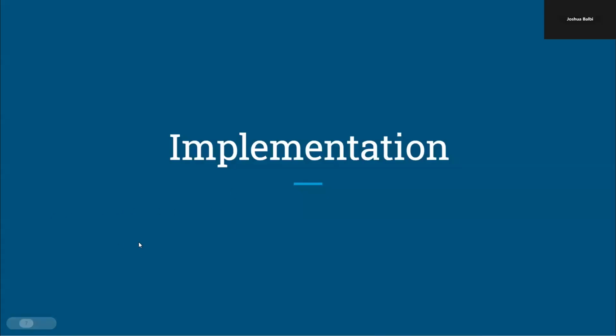So now we move on to the implementation of our project. In the implementation phase, we built a full wall following controller for the Turtlebot 4 using LiDAR sensing, a proportional derivative controller, and a logging and analysis pipeline so we could measure performance. I'll start off by showing how our code modules work together, and then explain the PD controllers and loops that drive the robot, and finally show a short demonstration of the system running.